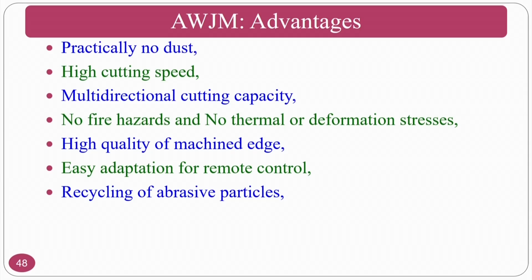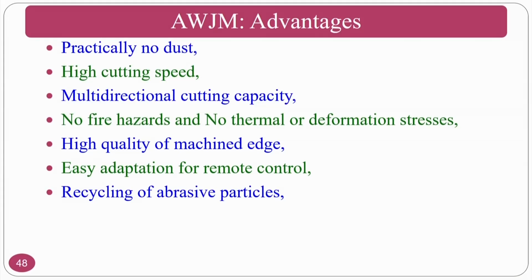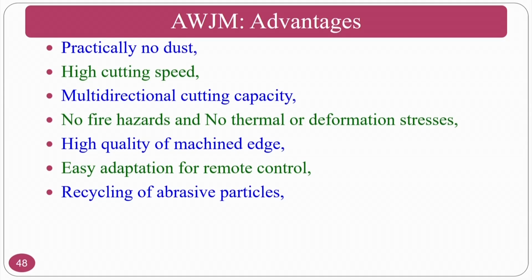Recycling of abrasive particles is always possible, because there will not be adherence of workpiece chip material to the abrasive particles, since the water lubricates the abrasive particles as well as cools the workpiece material. So, there will not be any high temperature generation, nor adherence of the workpiece material to the abrasive materials.